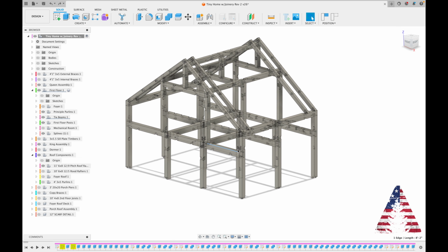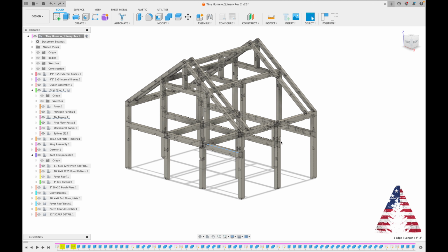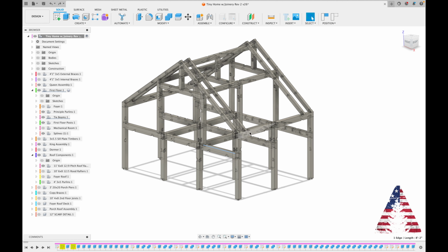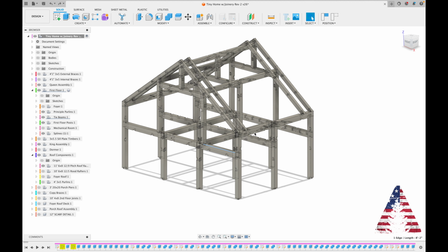And then with that design, you would have multiple of those assemblies. They're called bents, and you would put up 1, 2, 3, 4, 5, however long, and you would put tying members between those that really are just there to hold those bents together structurally, so they're all braced together to keep things from falling over.